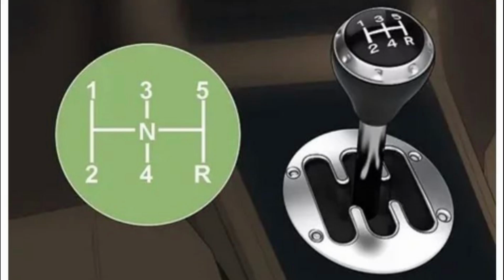Most electric vehicles use a single-speed transmission with 1 forward gear and 1 reverse function. However, a few high-performance electric vehicles may use a 2-speed gearbox to improve efficiency at very high speeds. The number of driving gears in an automobile varies according to the type of transmission system used. Manual transmission vehicles generally have 5 or 6 forward gears, while automatic vehicles may have anywhere from 3 to 10 forward gears. CVT vehicles do not have fixed gears, and electric vehicles usually operate with just 1 or 2 gears.